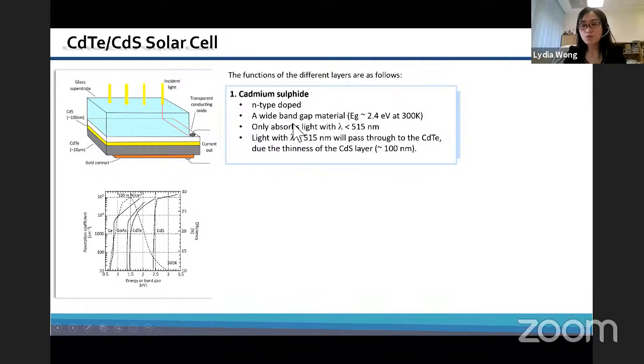The reason is because most materials are difficult to dope. Silicon is very unique because in silicon you can change the majority carrier by doping with boron or phosphorus, right? All of the other materials, they like to be P-type or they like to be N-type. They don't like to be both.